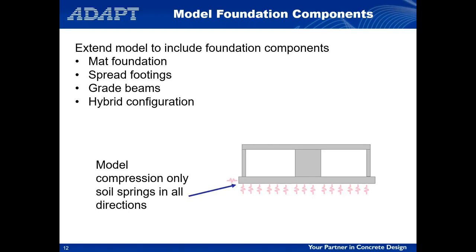So you're stuck with this challenge: even if I'm using another finite element program to do the PT design, now I have to take all of those forces, the hyperstatic forces, the redistributed dead loads, live loads, and bring all of those back through the columns and foundations.